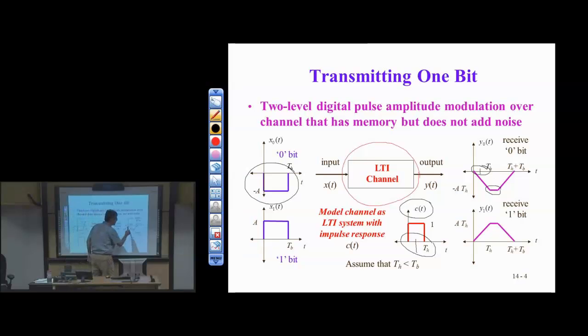All right. So I have to figure out some interval. If I'm going to average over the symbol time, or the bit time, I have to figure out when to start. So I could be safe and start at T sub h and integrate through T sub h plus T sub b. That's one symbol duration. So throw out the first so many seconds of received data and then start integrating. So I could throw out T sub h or half T sub h. Either one's fine.